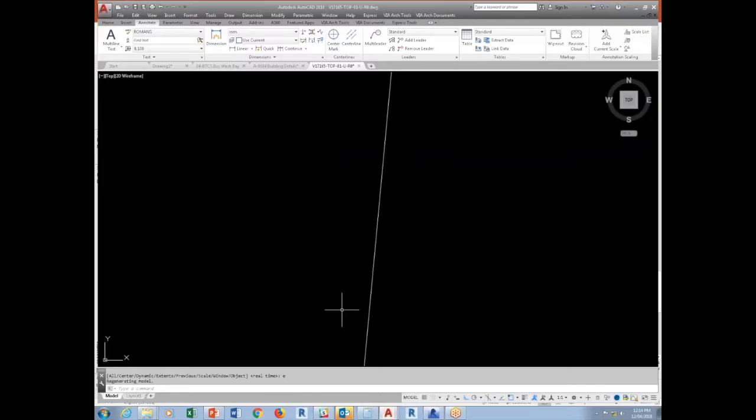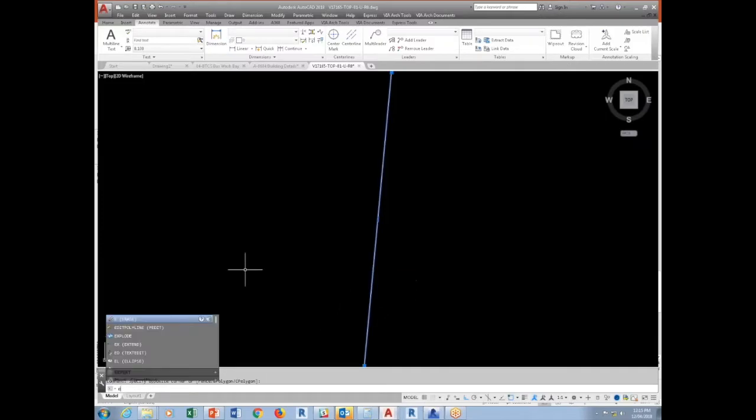Civil is going to use UTM, the Universal Transverse Mercator coordinate system, which is the world coordinate system. For us, we don't care about that. If you are doing it in Revit, you have to know where that position is going to be. For AutoCAD, if you're using AutoCAD files, you don't have to do much, but I'll show you one way to make that 0,0 closer without modifying this.